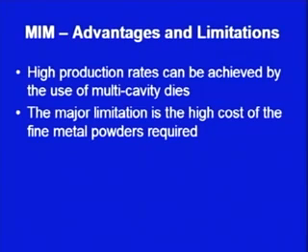High production rates can be achieved by the use of multi-cavity dies. So, the die can either have a single cavity or the die can have multiple cavities. So, if multi-cavity is there, the blended powder, which has been blended either with a wax or a polymer based lubricant, can be injected into a number of cavities, and the production rate subsequently can be very high.